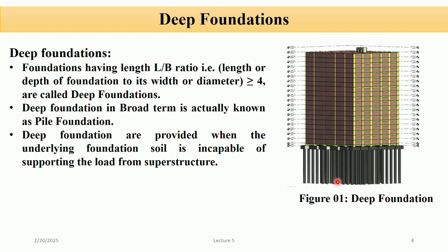Deep foundation. A deep foundation is a type of foundation that transfers the load of a building to a deeper, more stable or rock layer when the surface soil lacks adequate bearing capacity. It is used for construction requiring high load bearing capacity such as high-rise buildings, bridges, and heavy industrial facilities. We can simply define the deep foundation as one in which the length to width ratio is greater than or equal to 4. Deep foundation in broad terms is actually known as pile foundation.